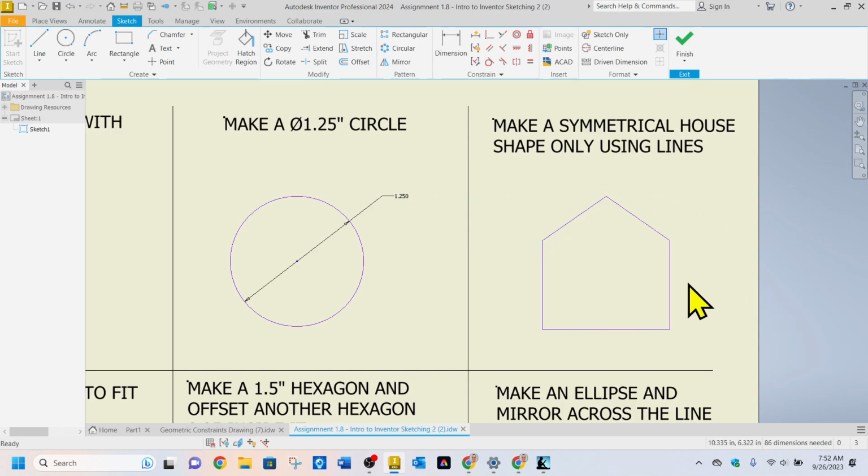And this is pretty close, but to make sure that it's totally symmetrical, I'm going to make these lines all the same. So I'll use the equal constraint up here. I'll go boom, boom, boom, boom. And then I'm going to make these two equal to each other, but not equal to those ones. So I'll just go there and there. Cool. So now if I were to stretch this out or anything like that, or if I change the peak there, it'll stay symmetric.